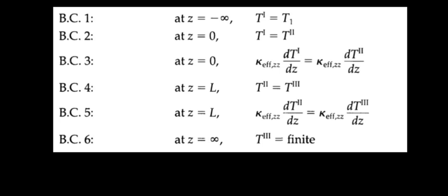Boundary condition 1, at the inlet of zone 1, where z tends to minus infinity: the temperature T approaches the feed temperature T0. The assumption of extending zone 1 to negative infinity is a mathematical idealization. In practice, it implies a region sufficiently upstream where the influence of the reaction zone is negligible and the fluid has reached a steady inlet temperature. This condition helps us to fix one of the integration constants that will arise from solving the differential equation for zone 1.